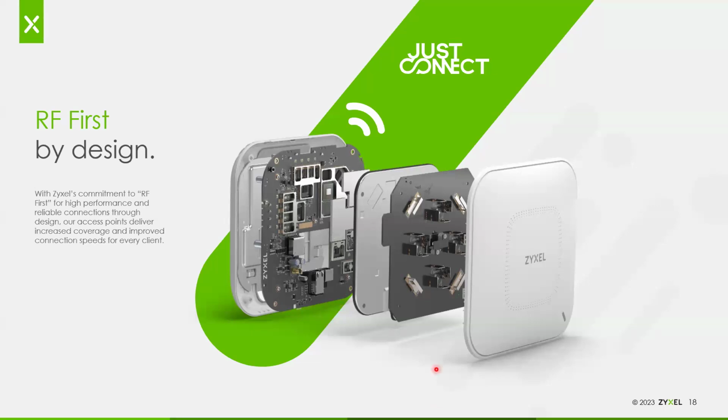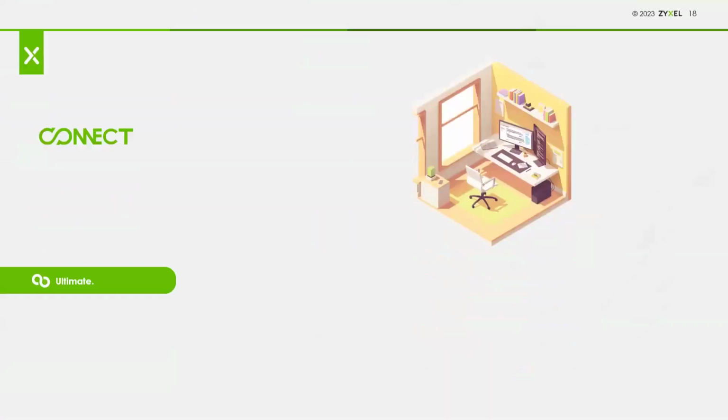The other thing we do is we do not mount our antennas directly onto the PCBA, but like most of our competition, including Ruckus, instead we have our antennas mounted on their own PCBA with a shield in between the main board and the antenna board to help create better isolation between the antennas themselves and any source of RF interference coming off the board itself.